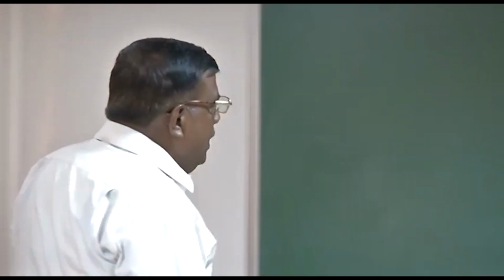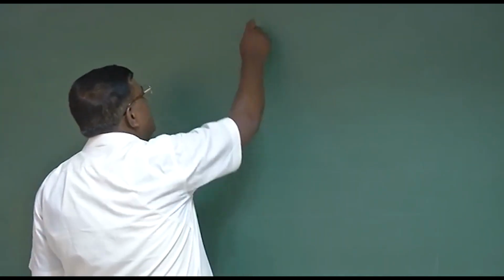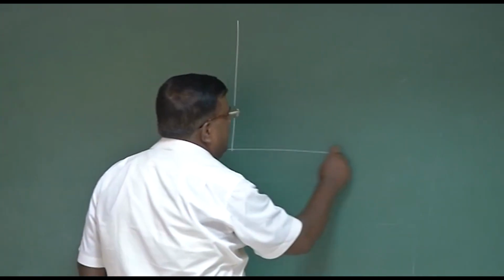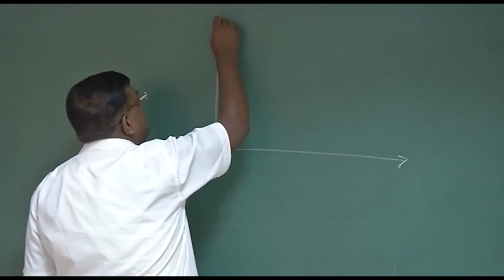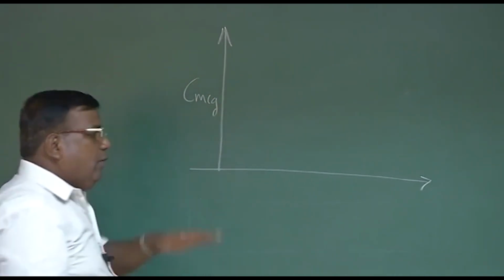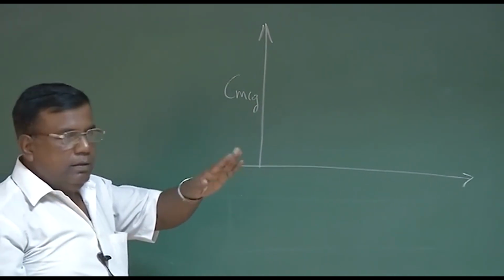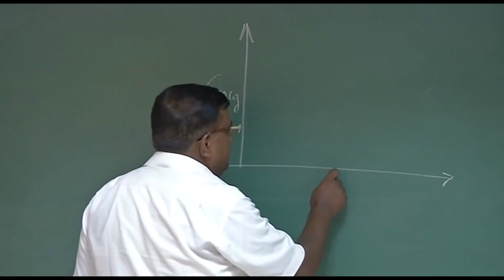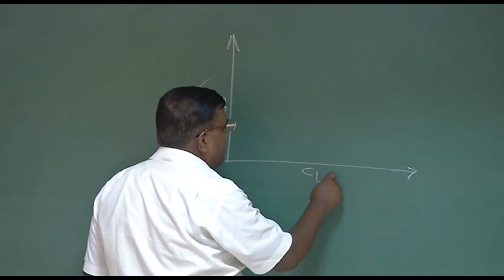The basic question which comes to our mind, whatever I may be talking, stability, control, trim, etc., is, can I fly this particular airplane at a particular CL? That means a particular alpha at a given velocity, at a given altitude. That is the question. And what we learned in a nutshell was, if I am talking about longitudinal stability, that is angular motion in the vertical plane, we have seen Cm versus Cl, or Cm versus alpha.